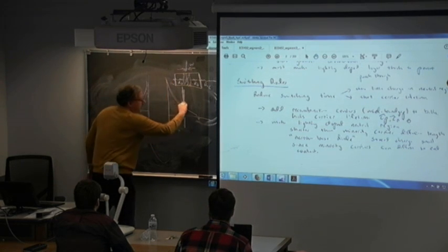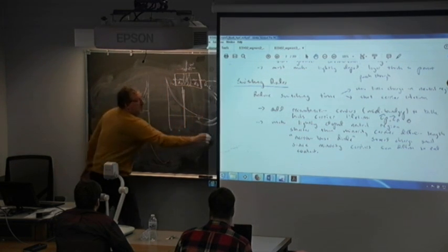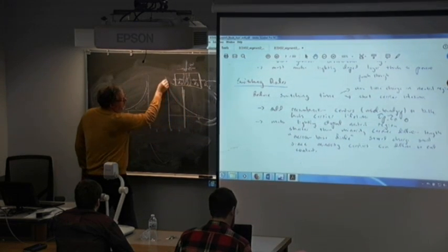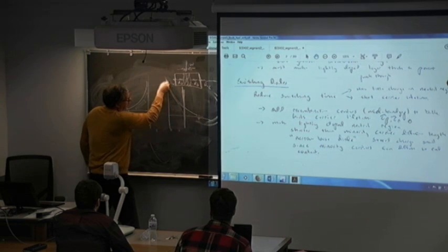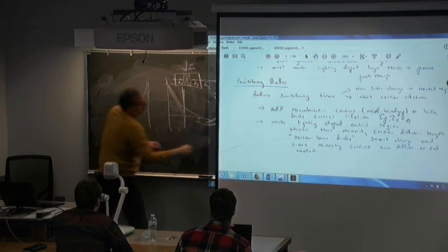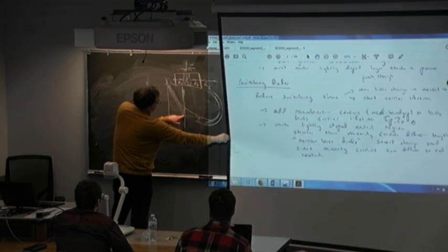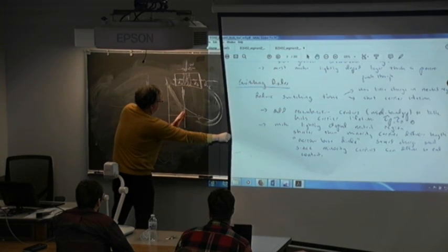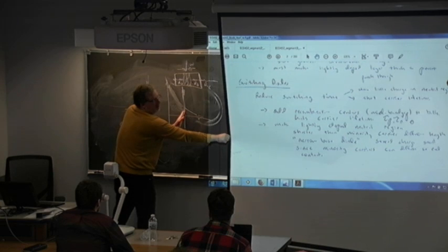So normally this would be the Gaussian distribution. And I put the contact here, so it basically means that the boundary condition, by putting my contact here, is that the semiconductor does not go all the way continuously here. It just stops here, and this is the surface of the semiconductor.